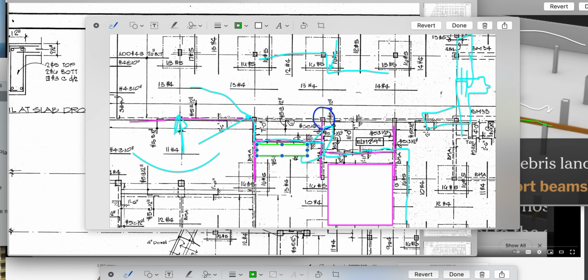So this is why this is a slab. You're looking at a slab detail 1'6" up in the air, 1'6" up in the air. And off of this pad, it's actually less. It's only like 7 inches off of the upper pad above this planter box. There's a 7-inch step right there. And then he added more pavers on top of it, and it comes out to be like an inch and some change. After they added the pavers out here, they also added up there. So it changes from a 7-inch step to a much smaller step down by default.